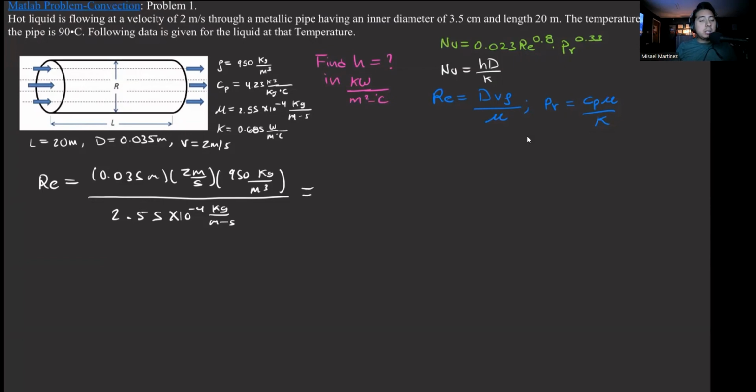If we plug it in, our Reynolds number should be a pretty big number: 26,784. For a pipe, we know that a Reynolds number above 2300 is turbulent. So for this pipe, the flow is pretty turbulent. But we'll use that for other calculations and different problems.